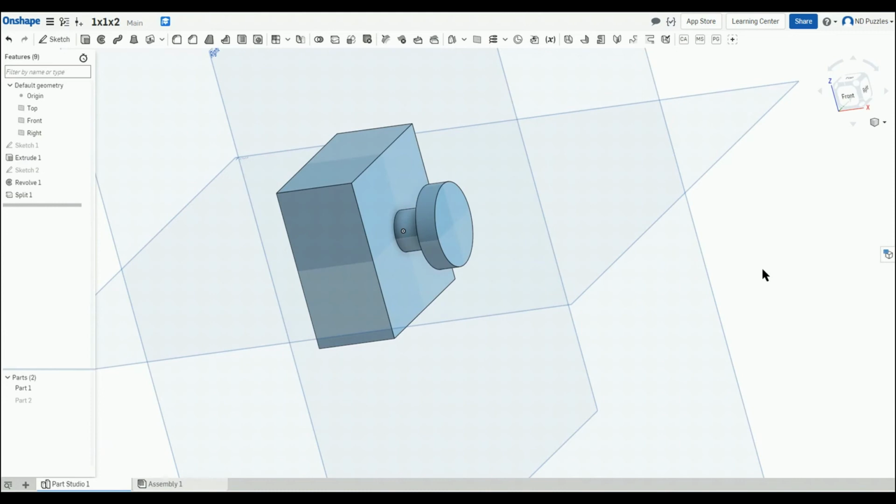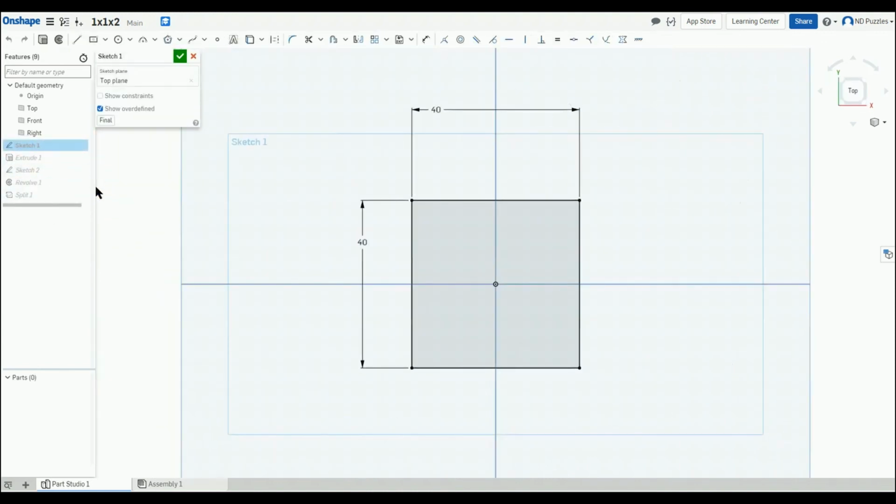Now choose surface. After that you can select every line of your hook. As a last step, click on the revolve axis, which is our dotted line. Now hit OK and be amazed. If you now hide the part, you can see that you will end up with a hook-shaped surface.